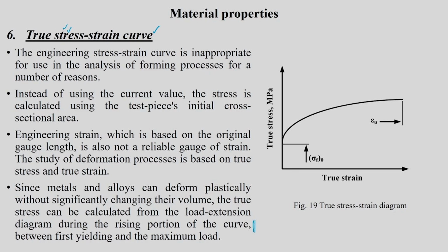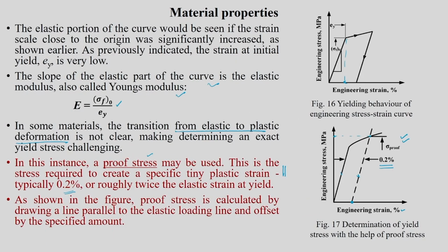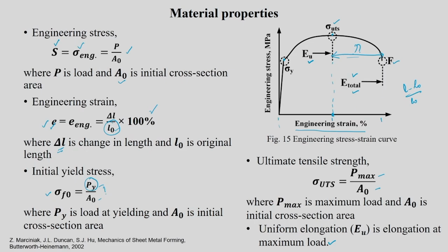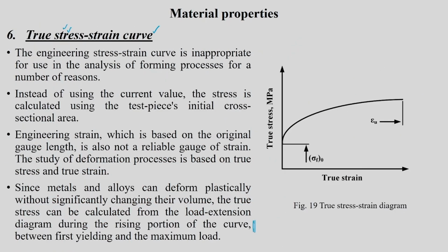So, what we do is we will define true stress and true strain, and that can be obtained from the load displacement graph or the engineering stress strain graph, and mainly in the plastically deforming region. Say this part, you pick up this part of the region, and you can get a true stress strain curve, which is what is shown in this diagram.